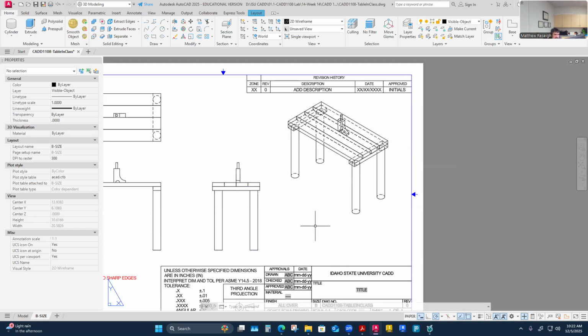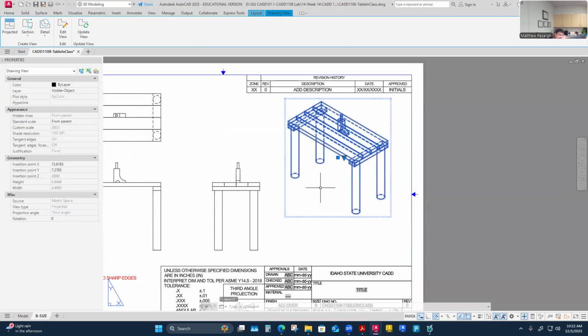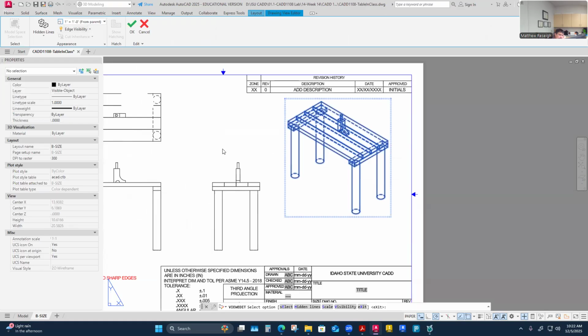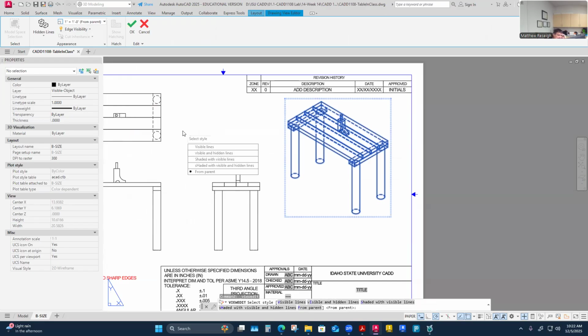What I do want to show is that sometimes when I do this, I don't love this kind of isometric view, even though that's how I'd want to display it in our normal orthographic projection views, show hidden lines and visible lines, right? That's our normal procedure. This is not how we normally do a pictorial drawing, so I could change this one, edit its view. Where's my little dial? Oh, it's here. I barely see it. I'm going to change its hidden line work.